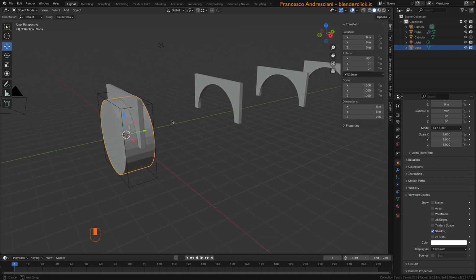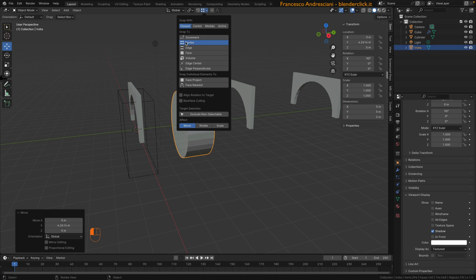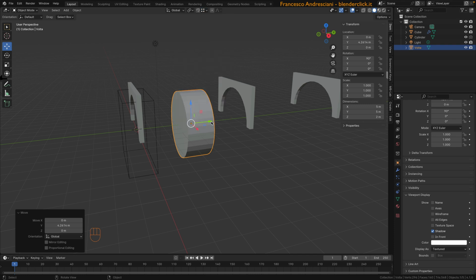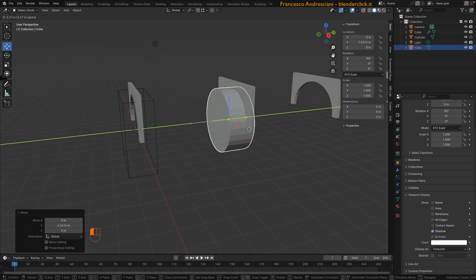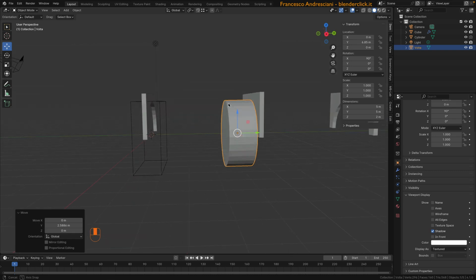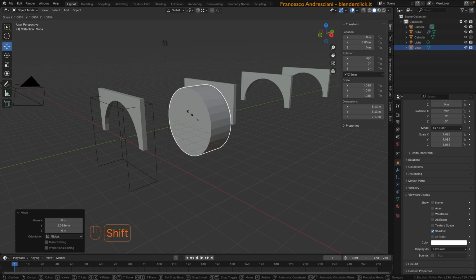What we do now is we move this cylinder. Let's enable the snap at the vertices. Then we drag via the displacement manipulator until we get against the other arc, then hold down the Ctrl key. By doing this, we are going right up against the next element of the arc. Then we scale our cylinder slightly, so S, and we're going to widen it a little bit. We can also go by I in this case.